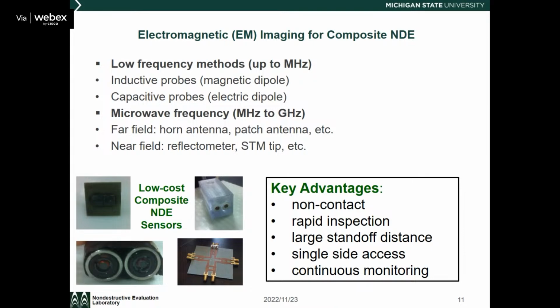It's very difficult to talk about radiation pattern versus frequency, right? For low frequency, you still can have a wave propagating in space, or actually not a wave but an evanescent wave pattern, or a phase wave pattern, when we're seeing inductive or capacitive. For inductive, for example, if we're talking about eddy current, it's not a wave equation. If you're talking partial differential equations, it's actually diffusive, right? It's a diffusion equation. You only have a first order time derivative there.